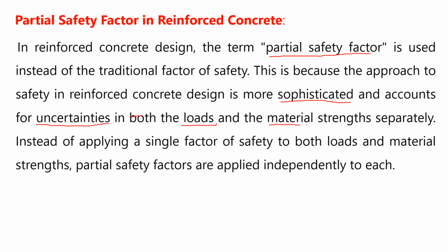Instead of applying a single factor of safety to both loads and material strength, we have separate factors of safety for loads and materials. So partial safety factors are applicable independently to each.